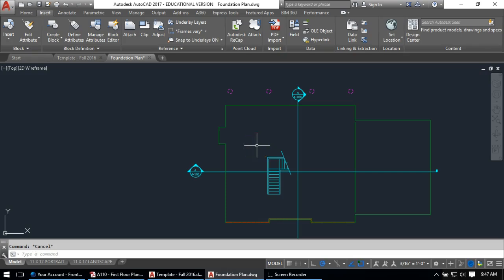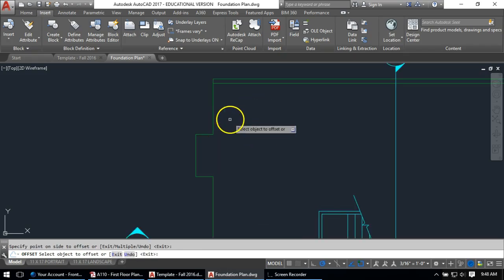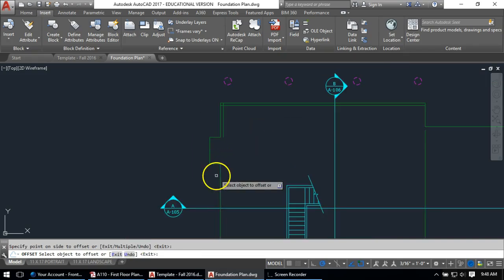Now, just like we did before, I can go along here and on the interior, just sort of offset these lines to get the interior door widths. And I think we were using 2x6s for the exterior wall, so that'll give us a 5.5-inch wall thickness. Actually, let's see, I think maybe it's marked. Actually, they're doing 6.5 inches because I'm sure they're counting some finished material on there. So it's marked at 6.5 inches, so I'm going to offset 6.5 inches. And I'm just going to offset these walls in.